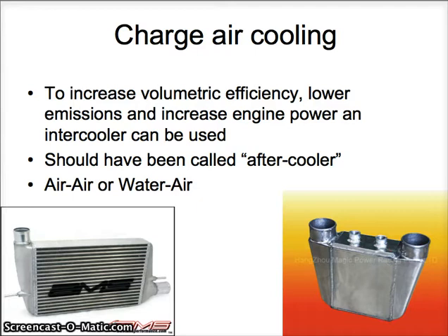When compressing the inlet air, it not only increases in pressure, it also increases in temperature. To prevent the engine from knocking or other intake components from getting damaged, there could be a need for charge air cooling. And the charge air cooler increases the volumetric efficiency, lowers the emissions, and increases the engine power by cooling the intake air.